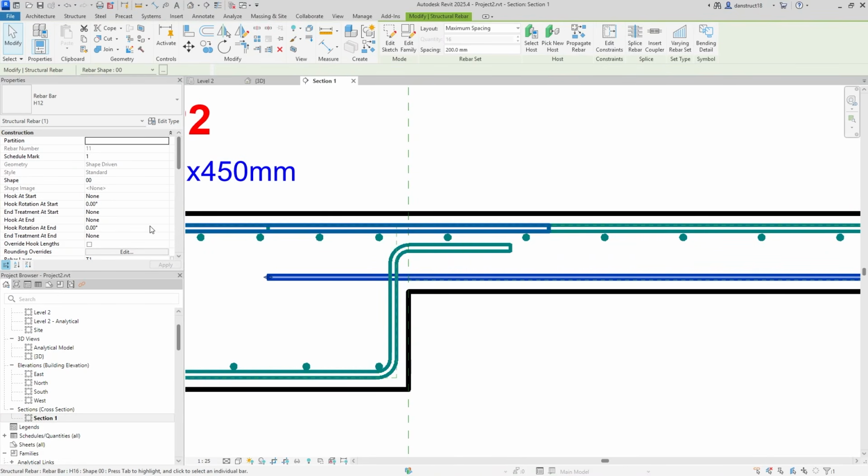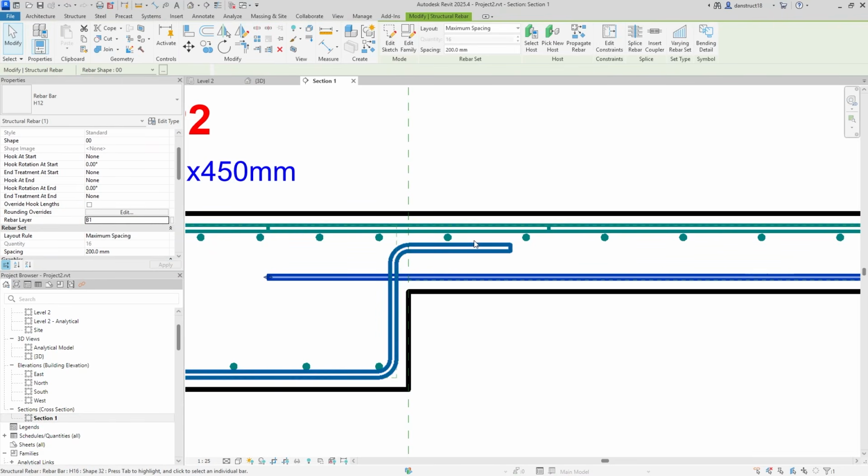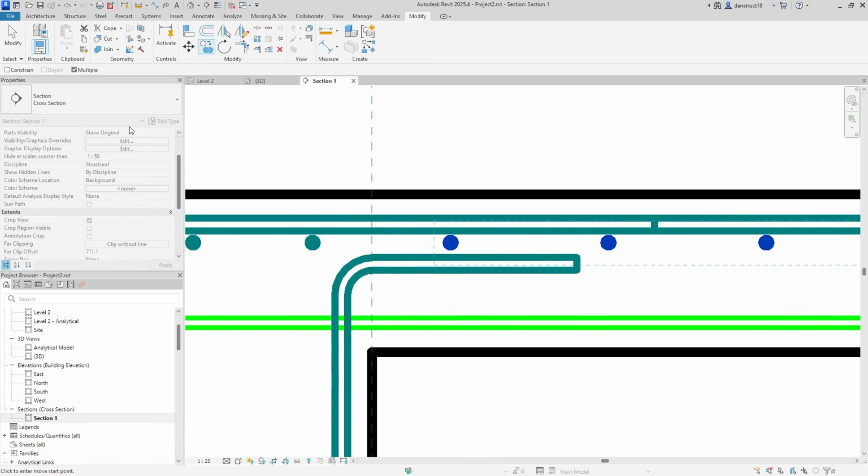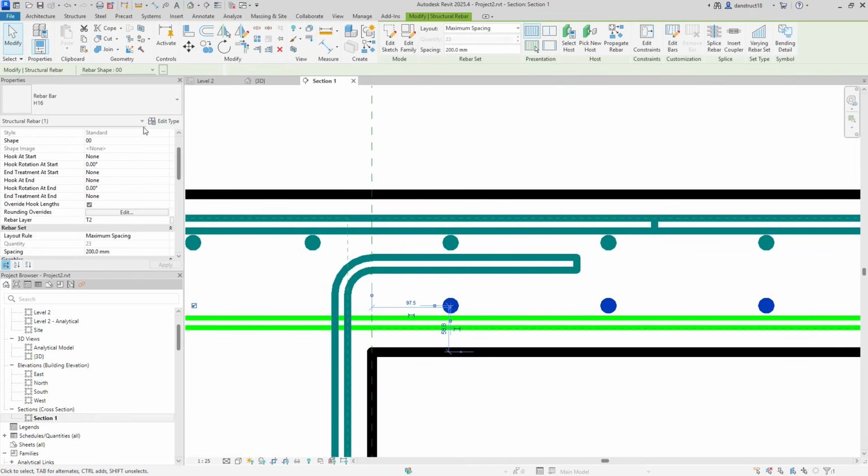All right, good. Here I'm going to change the name to B1. Click on apply, and I'll select this one as well. You can see the color has changed because in this template, it updates the color based on the type. I'll copy this one, which is the T2, and paste this one. There we go. I'll change this one as well to 10 bars. I'm going to nudge it here as well.